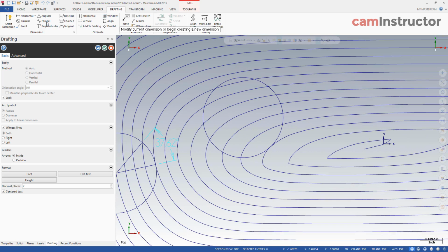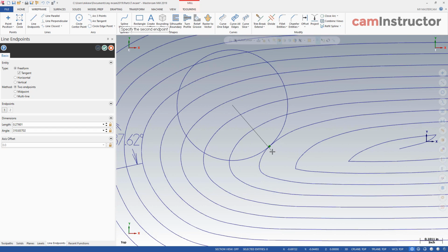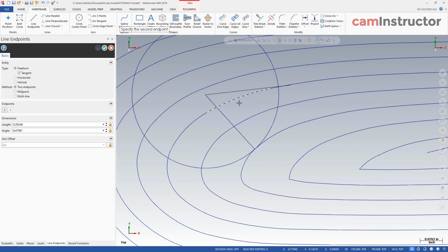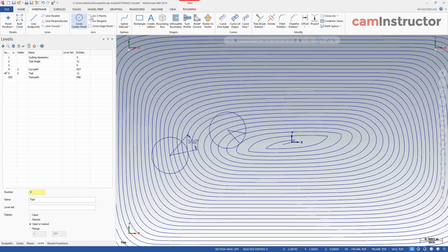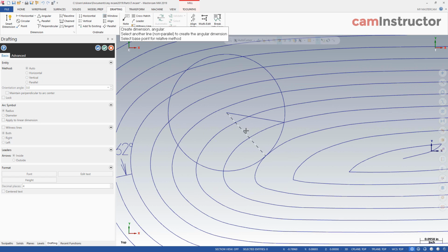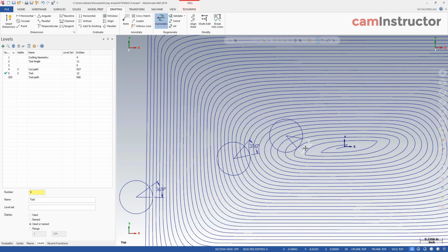Let's look at this circle in here now, or this cut in here. So find the center of the cutter there to the actual cut. Center of the cutter to new stock right there. We'll do a measurement on that. Angle of engagement. 38.19. Okay, so everything's still within 1.5 degrees, so very, very close.